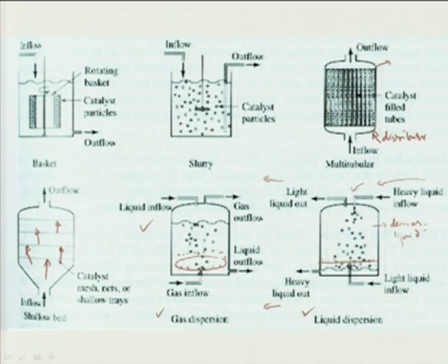This design is to maximize the contact area for gas liquid reactions by bringing together a gas and liquid as a thin film over a solid support. These reactors also offer increased thermal control due to the solid support, like a packed bed reactor, a countercurrent operating packed bed reactor using certain packing like Pall rings, Raschig rings, IMTP packings. In this case, the liquid is spread in the form of a thin film that flows over, or wets, the packing surface, and the gas flows at the bottom, and because of this spread of liquid over the packing surface, very high interfacial area can be achieved.